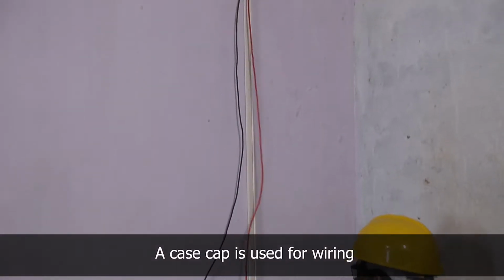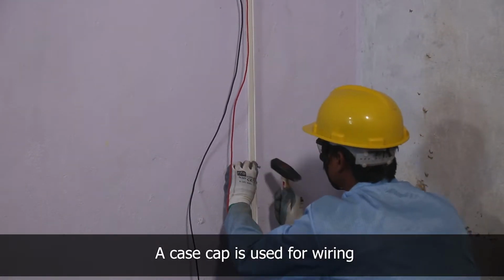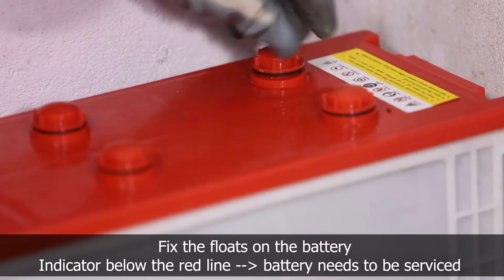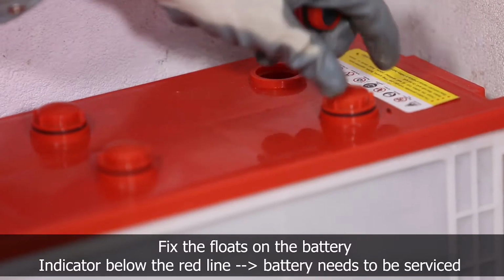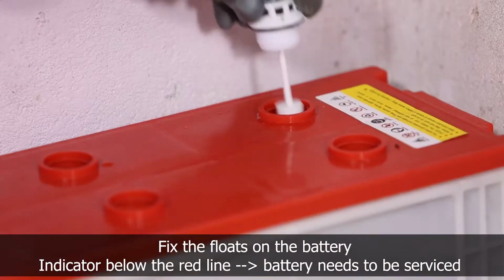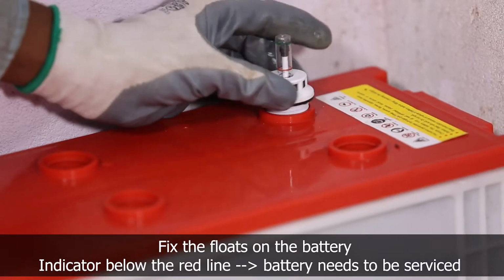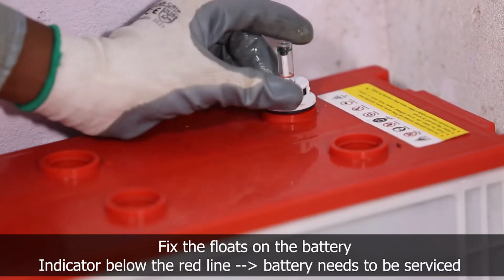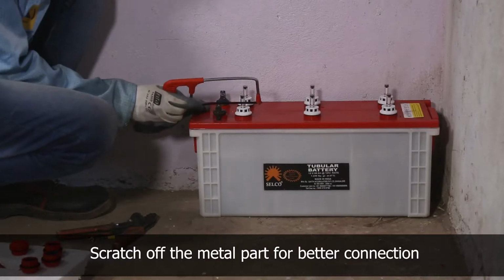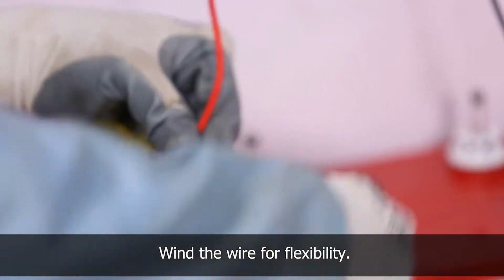A case cap is used for the wires from the charge regulator to the battery. Now, to connect the battery, remove the battery cap and fix the floats on the battery in order to check the water level. If the indicator is below the red line, the battery needs to be serviced. Scratch off the metal part of the battery for better connectivity. Wind the wire on the rod for flexibility.